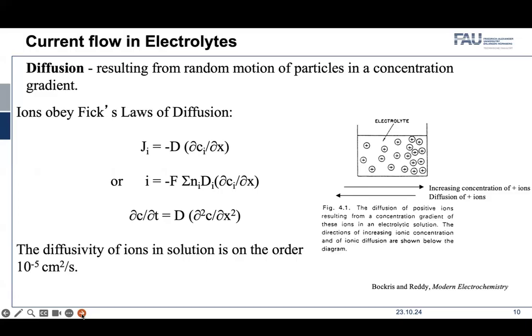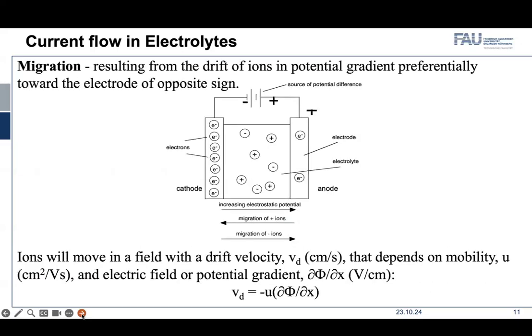So these are Fick's first law and second law. The first is steady state diffusion, where the flux is constant, and the second is non-steady state transient diffusion, where concentration is changing as a function of time.